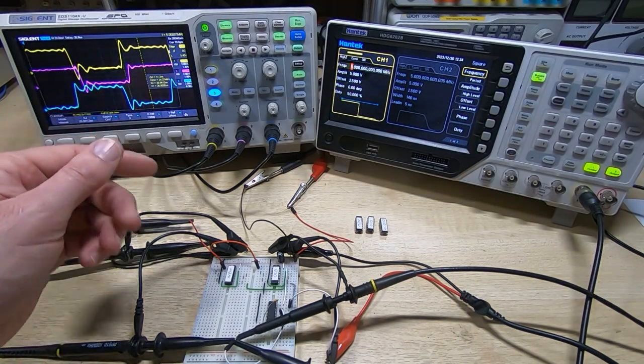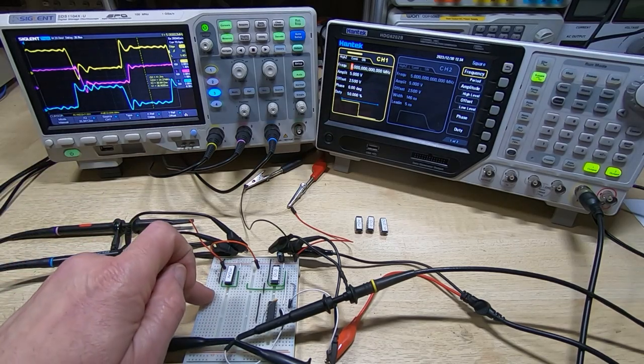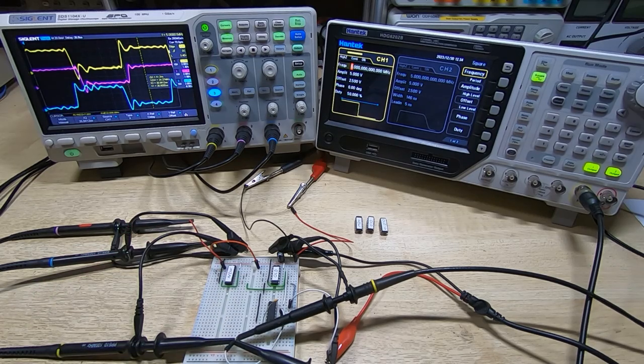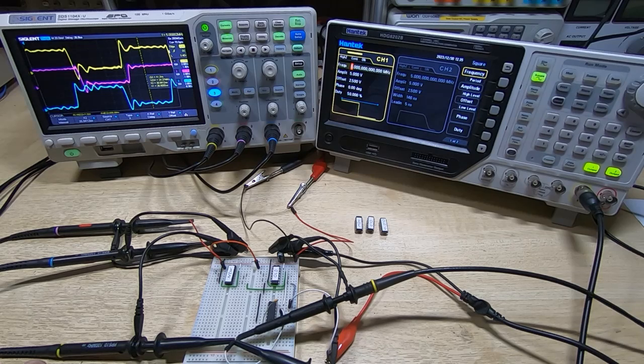What you can do is, you've got two probes, put one on the input of a device, one on the expected output, and see what the delay is. And if you're getting something that's obviously way too long, then it's going to potentially indicate that the device is failing. Could of course mean that the device it's feeding into is drawing too much current, but either way you can look at which of those two it is and start to investigate the devices.